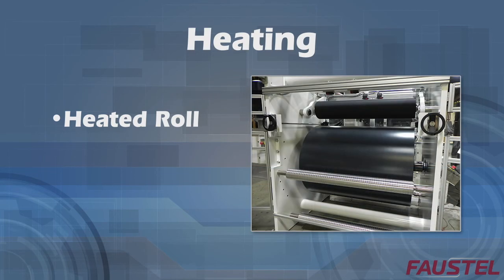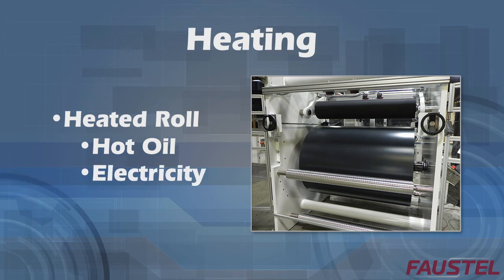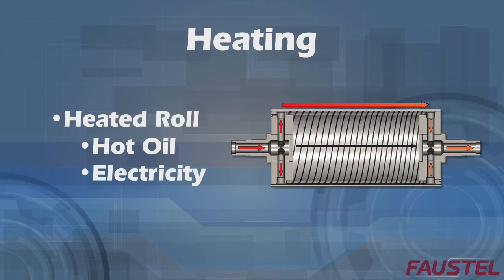Uniformly heating a laminating roll is not a simple matter. Careful design is needed to ensure the typical 2 to 3 degree maximum temperature deviation. These techniques include building a roll within a roll, the so-called double wall roll. The heat transfer medium is channeled between these walls using a progressive spiral channel, which provides a more consistent controlled heat flow that minimizes stagnant areas and enhances heating uniformity.